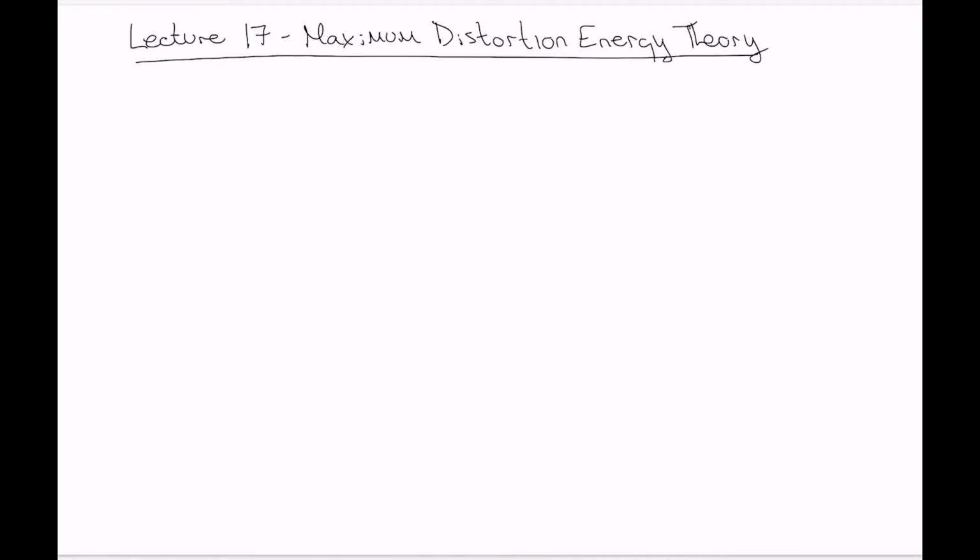Now, the absolute maximum shear stress theory and the maximum distortion energy theory can both be used to predict failure in ductile metals. But they're a little bit different. The absolute maximum shear stress theory is great because it is so simple and easy to apply. Mathematically convenient, suitable for sort of back of the envelope calculations, and it's pretty good. When you compare its predictions of when failure will occur to an actual test, it lines up pretty well, but not perfectly.